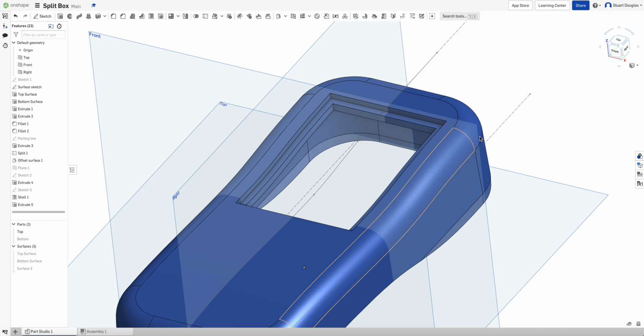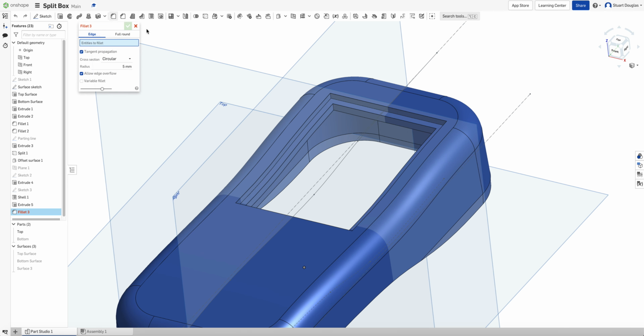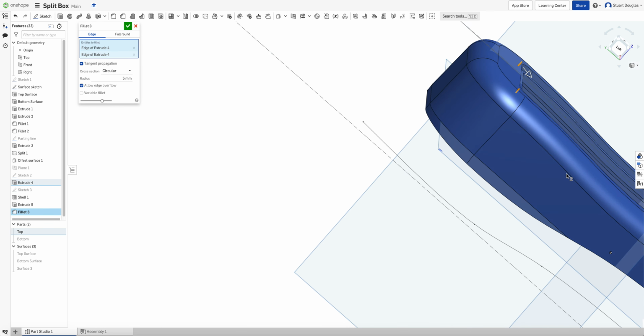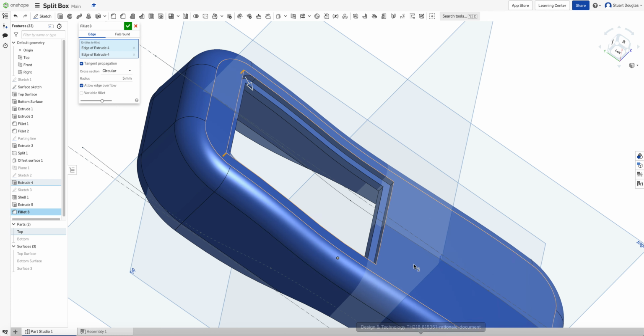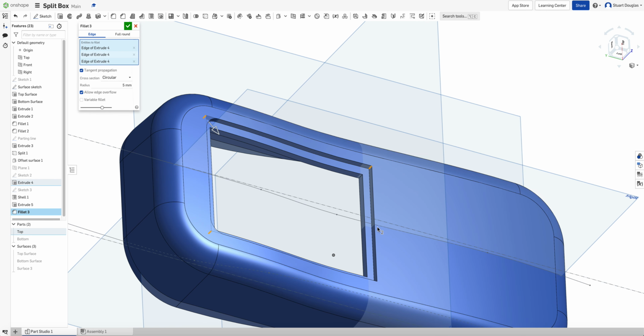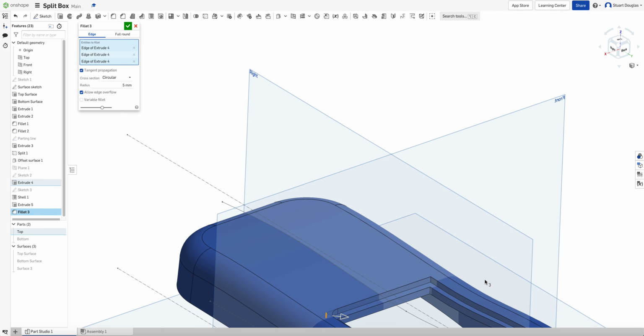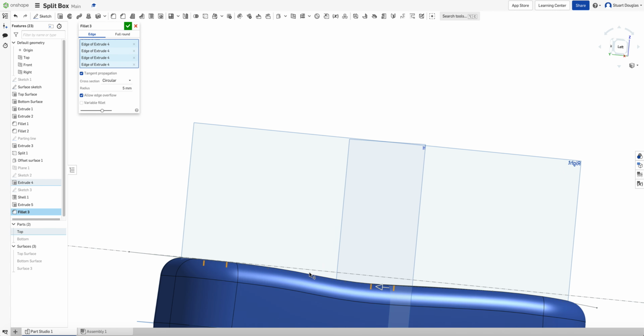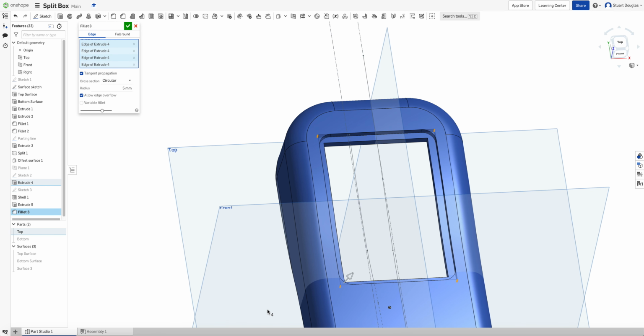So the last thing I just want to do with this top section here is just neaten it off to match the outside with some fillets. So if I use the fillet tool now, we'll start with the top edge. Let's start with that. And what we're trying to do is soften the shape. Okay, so these are like adding the small details. Rather than having a sharp edge, you yourself probably wouldn't buy products that had sharp edges. You want them to be softer. So we've got now, like that, a nice soft edge.